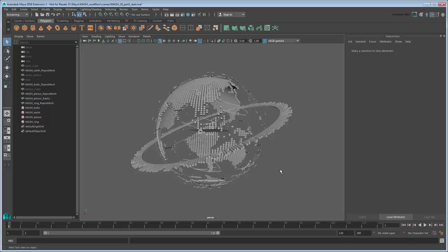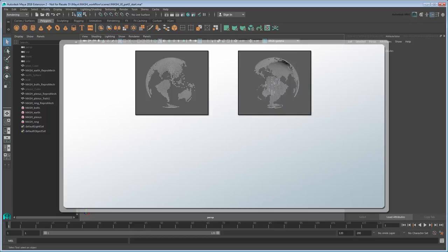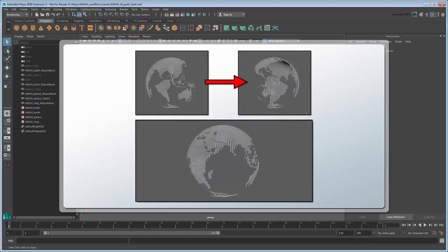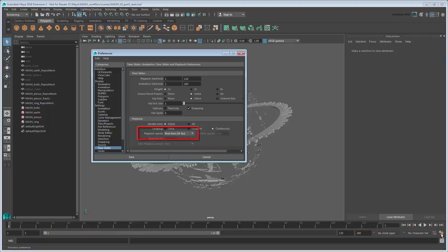Animating in Maya is much like animating in traditional hand animation. You start by snapshotting a scene in a certain state at one point in time, known as keyframing, then snapshot a different state at a later point in time, letting Maya fill in everything in between. Maya keeps track of time via the time slider, which is divided into frames rather than seconds. By default, 24 frames makes up 1 second, though this is customizable. For this tutorial, we'll leave it as is.